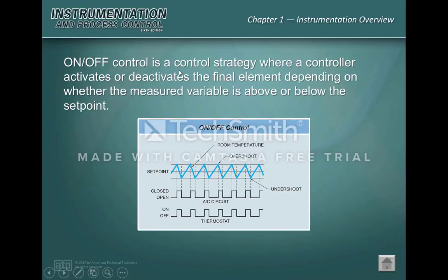On-off control, so you can think of this as your air compressors. We have a set point, say 120 psi, and we can go over and under it. Another way it's used is in heating and air conditioning. So here's my 72 degree set point. We may get up to 74 and get down to 73, and it bounces back and forth.